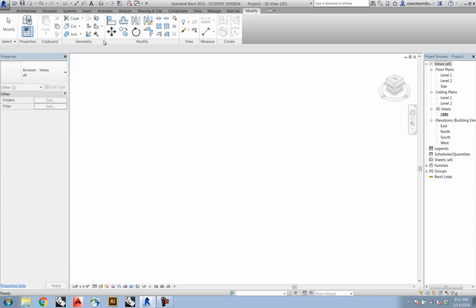do your typical kind of drawing tools, right? So cutting and joining, aligning, offsetting, move, scale, rotate, 3 different trim extend tools, scaling, array, splitting objects, pinning and unpinning, which is like locking them. This align dimension tool is useful because it's actually parametric. It's something that defines a relationship between 2 objects and will maintain that linkage when you put one of those dimensions onto the object.